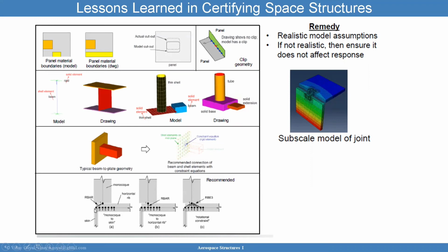Here, that's one way to model it, where you have a rigid bar connected to this skin. However, that's going to produce incorrect results because you're going to have extra rotation. The more appropriate approach is to connect the whole footprint because that's how it looks in real life.